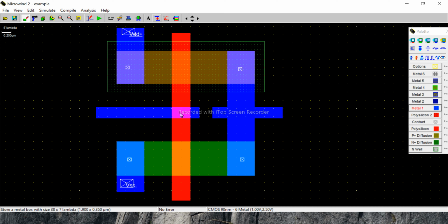If it is different, you can find it in this fashion. So now these are two different kinds of layers. Now we are supposed to make a contact between this metal 1 and also polysilicon. You can find that one over here. This is a metal and poly contact. Take this one and place it over here and give the input terminals.